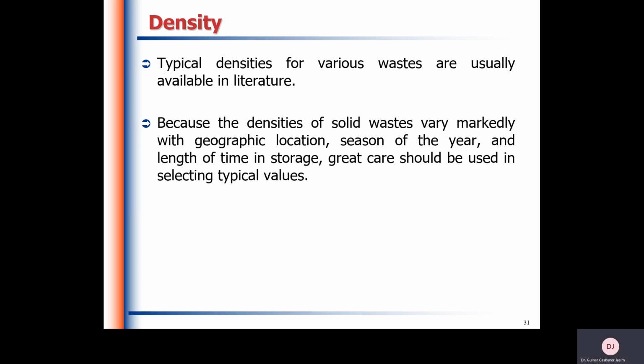Typical densities of various wastes are usually available in the literature. Because the densities of solid waste vary markedly with geographical location, season of the year, and the length of time in storage, great care should be used in selecting these typical values.